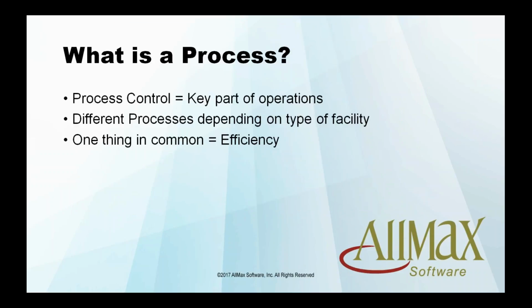And with that, there's one key element to all these processes, and that one thing is efficiency. It's how well we are doing to make sure that the program works fine and that our system is working the way it is designed. We look at design criteria, a lot of which you will see in treatment plant setups. If you look at O&M manuals, they base it on our loadings and our removals in a treatment plant, or what our detention times are in given tanks. Like in a water plant, we may have a flocculation chamber that has a set amount of detention time that we have to meet so that it runs efficiently.